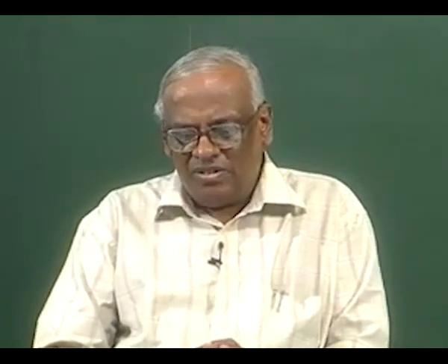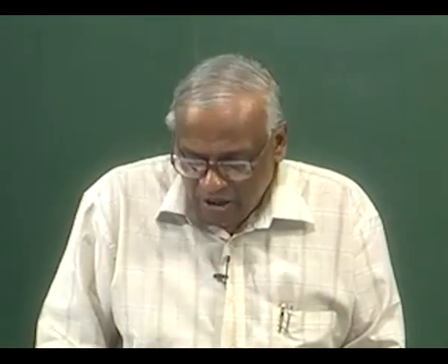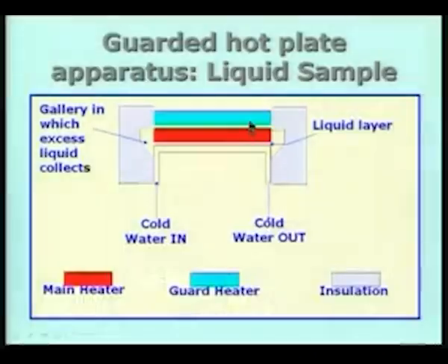In the case of liquids, I must have heat transfer from only one side, that is in the up and down direction, unlike in the other case where we had both up and down directions. Here we have only one direction, and the main heater is protected or is guarded by the guard heater, which prevents heat transfer from the top altogether.